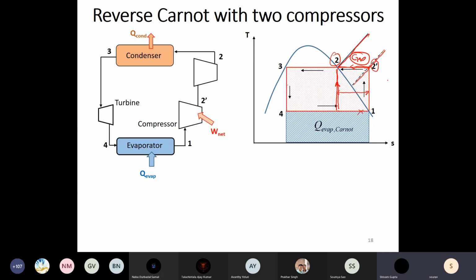So now this process becomes very, very slow. First of all, we do not have a compressor which works in an isothermal manner, because all the compressors will have some finite speed. When you compress a gas at a finite rate, it will not go to 40.0001 degrees and wait for you to cool, and then again you will move.